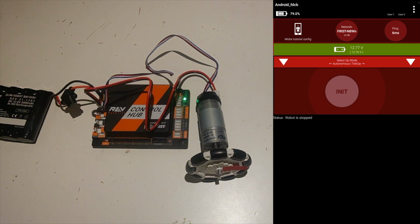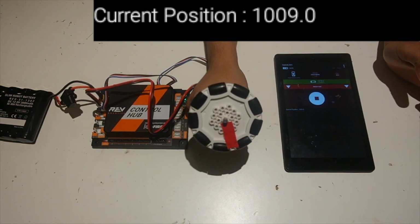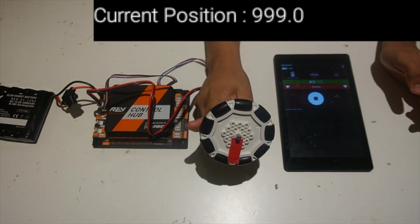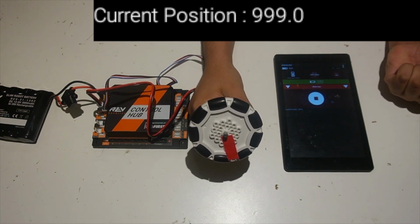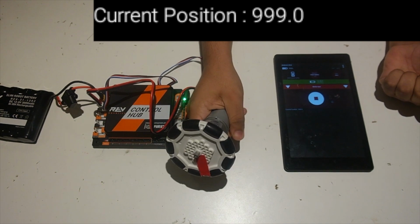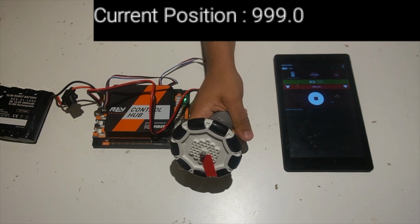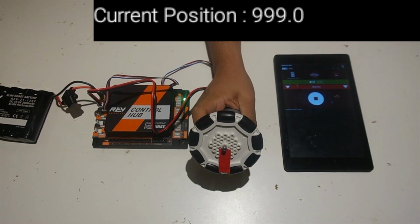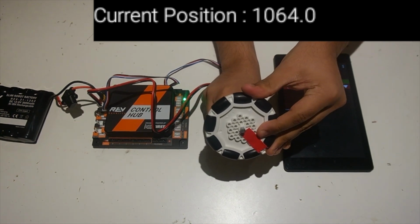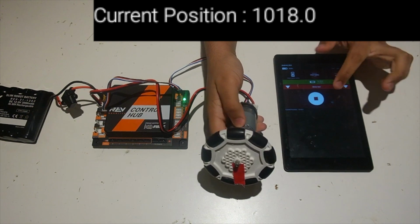So now I'm going to show you how this program works. First thing I'm going to do is select motor test and hit initialize. This is still using run to position. If I hit play, you can see that the current position is now 1007, and I can move it in a small range around 1000. And that's fine. You can tune the PIDF values a little bit more; take a look at First Global's tuning guide. But otherwise, that's less than a degree when it's at 999. That's a very small amount. That's really good. And you can see you can use this to actually get the encoder position. So when I spin this, I can get the encoder position out of that, which is really nice.